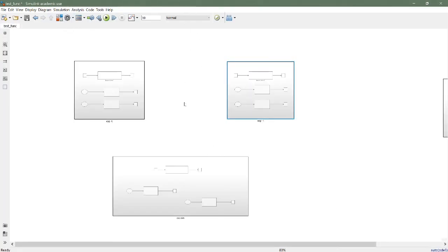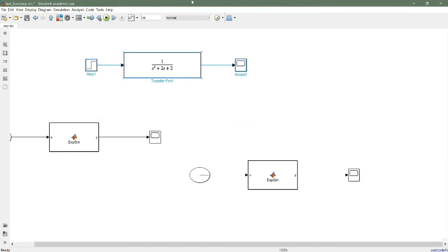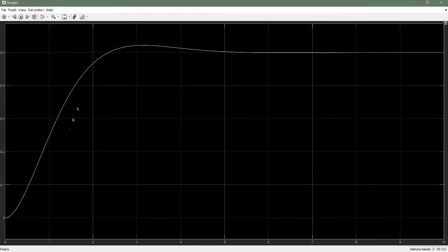And this is a very interesting signal, and it is like this. And if you remember, this is actually the Laplace transform of e raised to the power minus t multiplied by sine of t. So when we do this step signal, it looks like this, right? It's also very different because we don't see any sine wave or anything else over here. Also it doesn't go to 0, right? It just stays at 0.5.